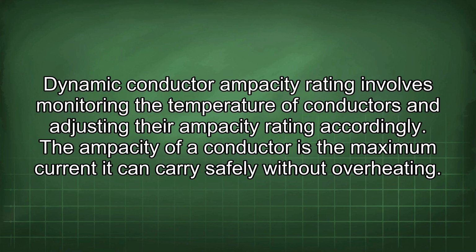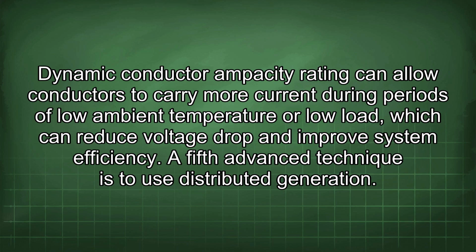The ampacity of a conductor is the maximum current it can carry safely without overheating. Dynamic conductor ampacity rating can allow conductors to carry more current during periods of low ambient temperature or low load, which can reduce voltage drop and improve system efficiency.